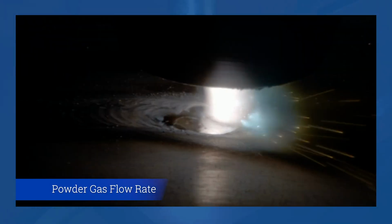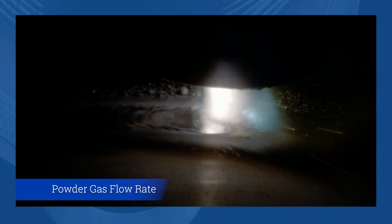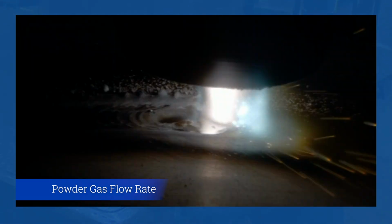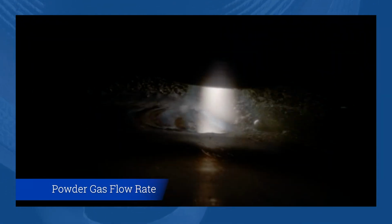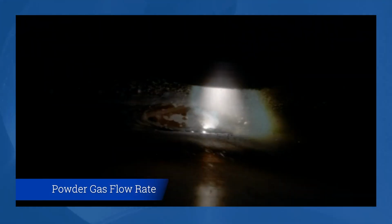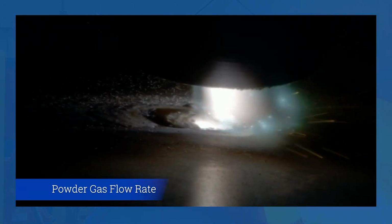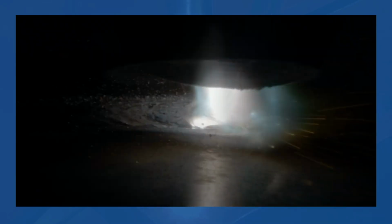And then we'll go the other extreme. We'll reduce it. Now, what this means is we're no longer going to be transporting powder through the torch to the part. So you start to see that we're not creating the weld volume that we're looking for. This is hard to differentiate with insufficient powder because that's how it manifests itself. So we'll go back to the correct setting. We get a good weld. This is a critical variable you have to set with your eye.